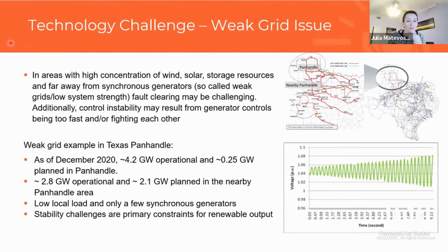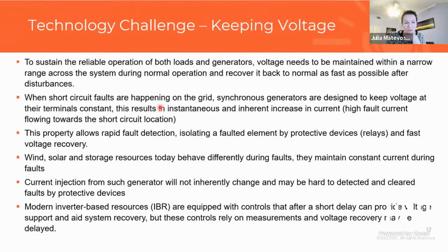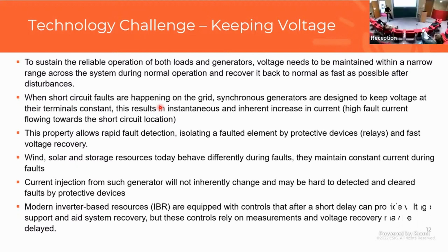Yes, and also, the same issue will apply to what I showed with disturbances that we're seeing on the grid today with grid following inverters. The same issue will be there with grid forming as well, that there is no certainty in the models, and that all controls and all protections that matter are included in the model. So I think there'll be a learning curve where we'll see the same kind of things happening where they behave unexpectedly. So that's something we need to learn. Okay, please, Simon.